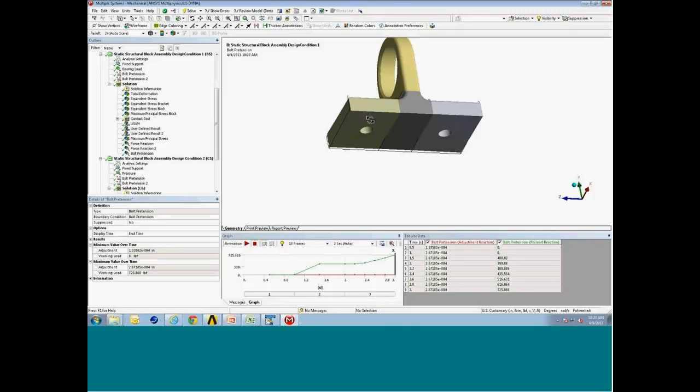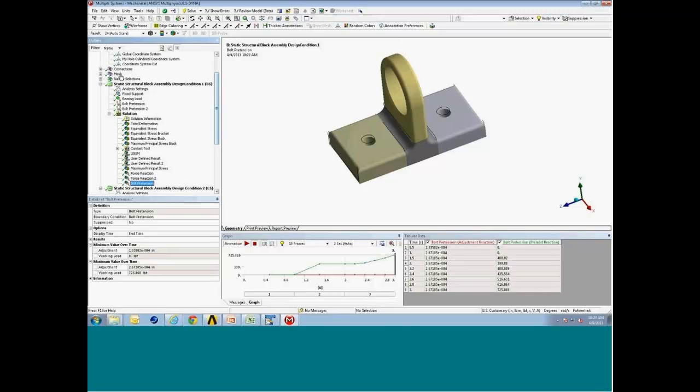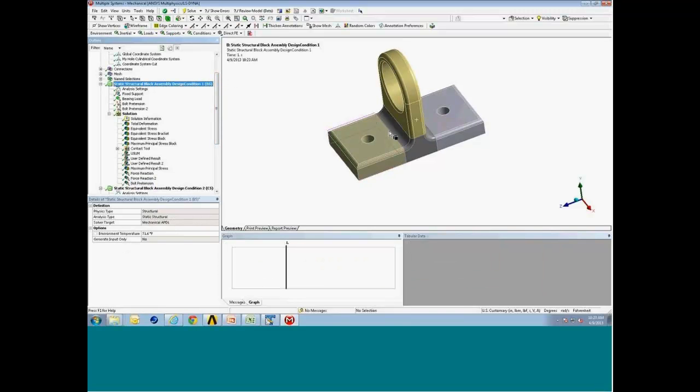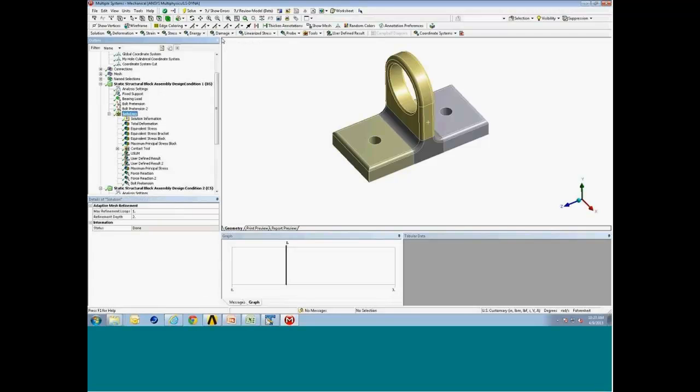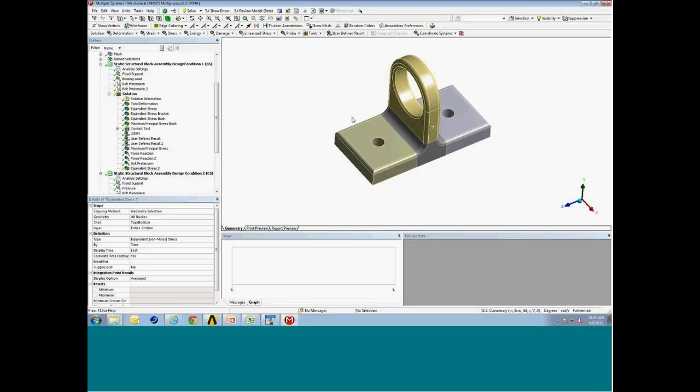Right. The next thing I'd like to do, in some of the new version 14.5 capabilities, is show you the capability of looking at just node and element results, accessing those types of results. You can do this directly within a specific static structural example here by inserting a results quantity. Let's say when we want to look at a key component or results in a local area, we may not want to scope it to a surface or a body. We just want more of a local area. So let's scope equivalent von Mises stress results to only certain nodes and elements in the model.